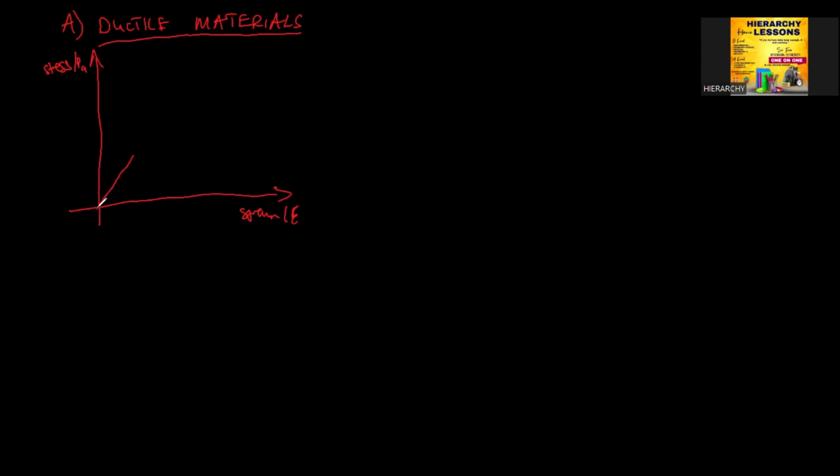Here it's a straight line for ductile material, and then we have something like that. Here is B, which is called the UTS, the ultimate tensile stress, and here is P. Here it's Y, and then we have a point here that's E. Then 0, 0. Along the graph, let's explain from O to P.